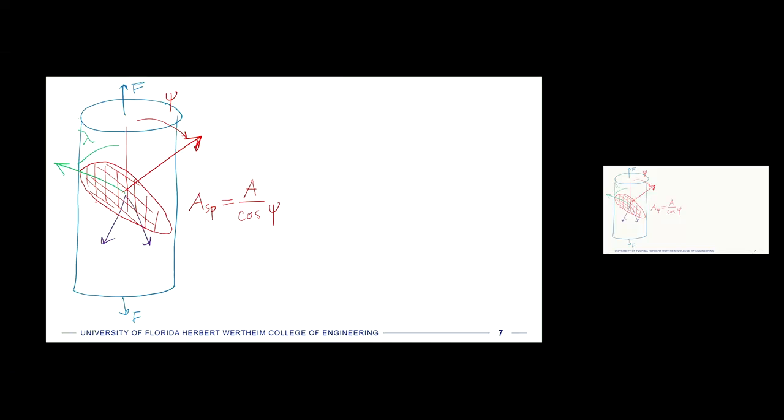So that was my 5-minute bell. What I'm going to end on today is that there's a threshold shear stress that I'm going to call tau r, because it's resolved into this shear plane. In the shear plane, according to the slip direction, which is defined by lambda, let's just say it's defined by my original green arrow there, that means there's some shear stress also applied in that direction. So that's our tau r. That's what we are going to have an expression for here.